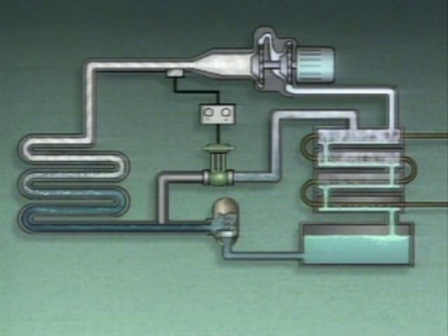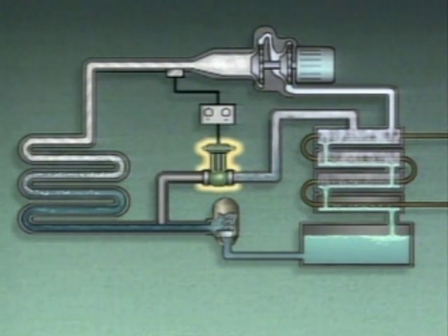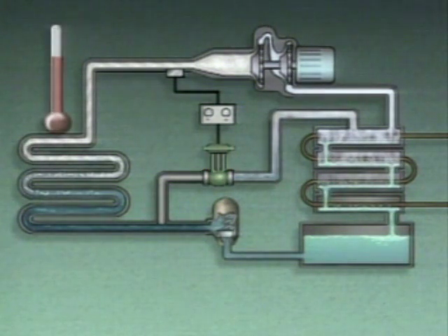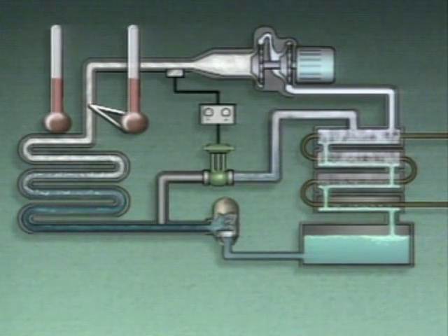The flow of refrigerant through the bypass line is controlled by a control valve to maintain the temperature around the evaporator. If the temperature around the evaporator gets too low, the temperature of the refrigerant flowing to the compressor will drop.